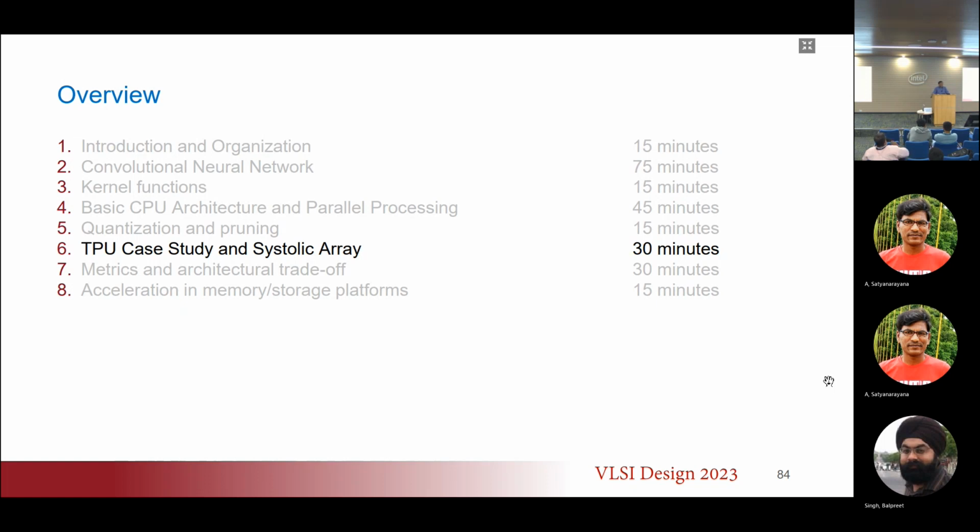And the effects of tiling on the data flow and hence the controller. Yeah, it's a very good question. When you have tiled the matrix, then the question becomes, how will you fetch the tiles and do the computation, right? There is a way to fetch the tile and do the computation.